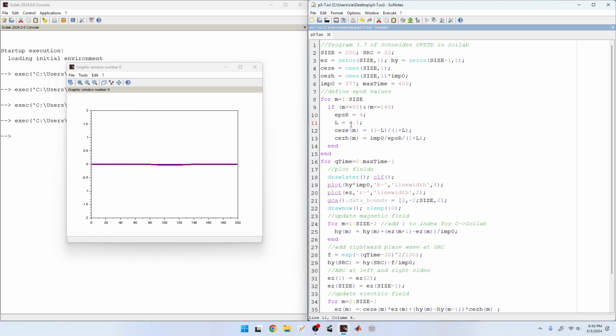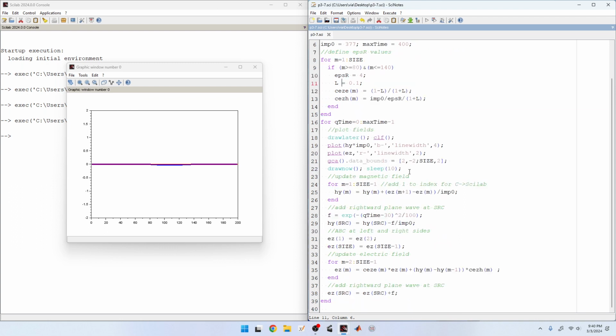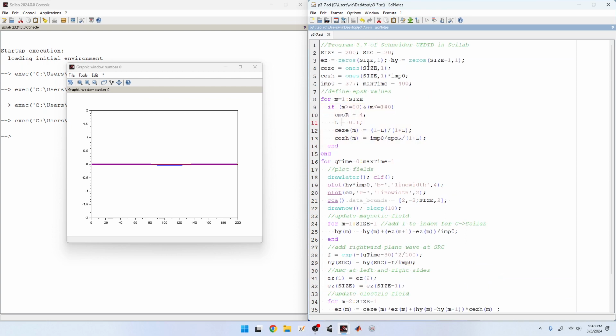So if we also included the magnetic conductivity, now we could vary electric conductivity, magnetic conductivity, dielectric constant, and relative permeability arbitrarily with position. And now we can solve quite complicated one-dimensional problems. In fact, we can solve the most general one-dimensional problem with this code, right? And we didn't have to change very much, right? So there's just about one page of code here. We made small incremental changes as we added these different features into our code.